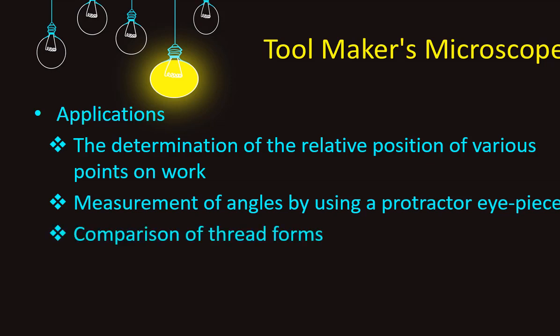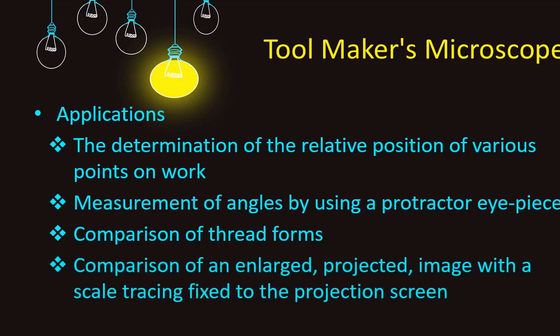Third one is comparison of thread forms, and the last one is comparison of an enlarged projected image with a scale tracing fixed to the projection screen. So these are the applications of a tool maker's microscope.